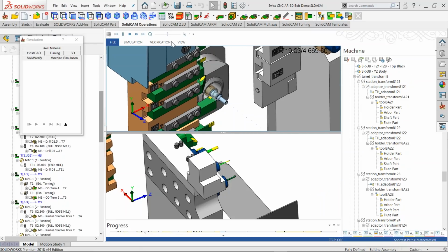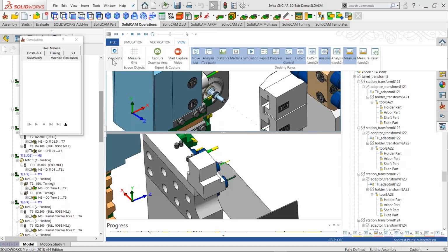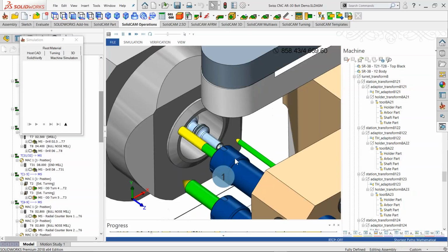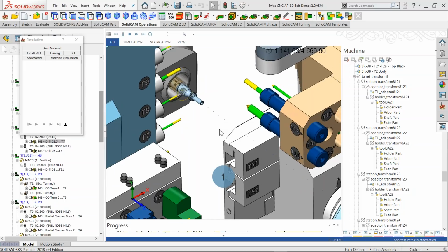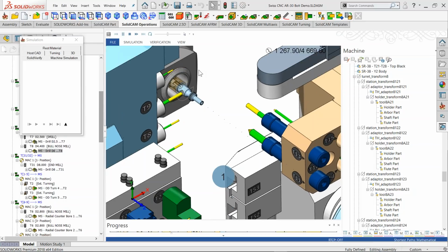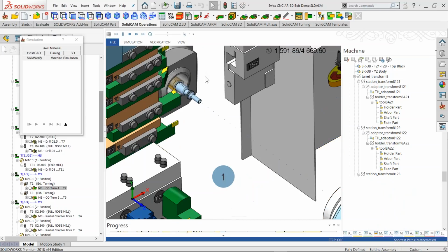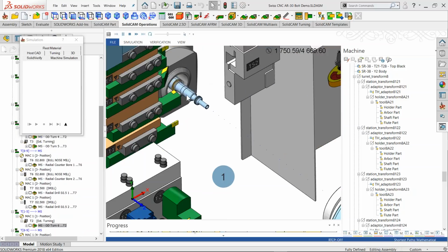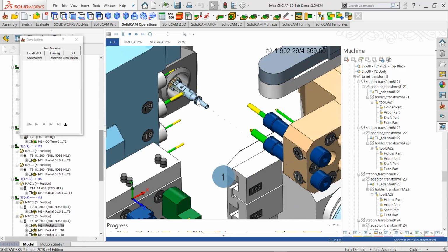We just released the part. We'll continue everything on the main spindle. In this case, I can stop it over here, go to View, and change to maximize. I'll run the part completely, so we can see also the part transfer. And for the end, guys, I would like to show you the G-code a little bit, how easy it is to generate it. Let's wait until the operation goes to the end. It's nice to see the part transfer.